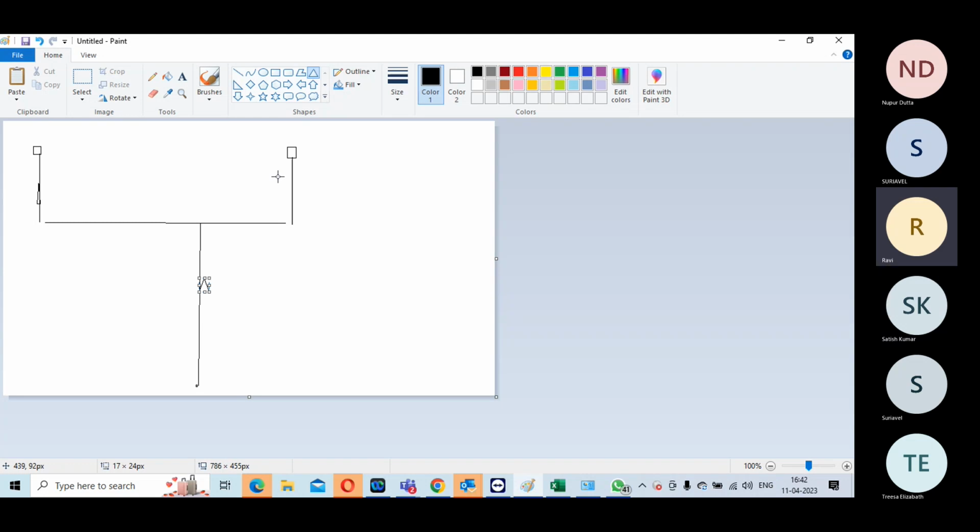When you're defining a clock stop pin, you have to give the clock balance at that point that you expect. That is the endpoint, but you can define what the clock skew balance is. Like you have already built 1 nanosecond of clock tree, so I'll say clock exception of minus 1. I expect a clock balance point of minus 1 nanosecond at this point. That's the way you will define it.